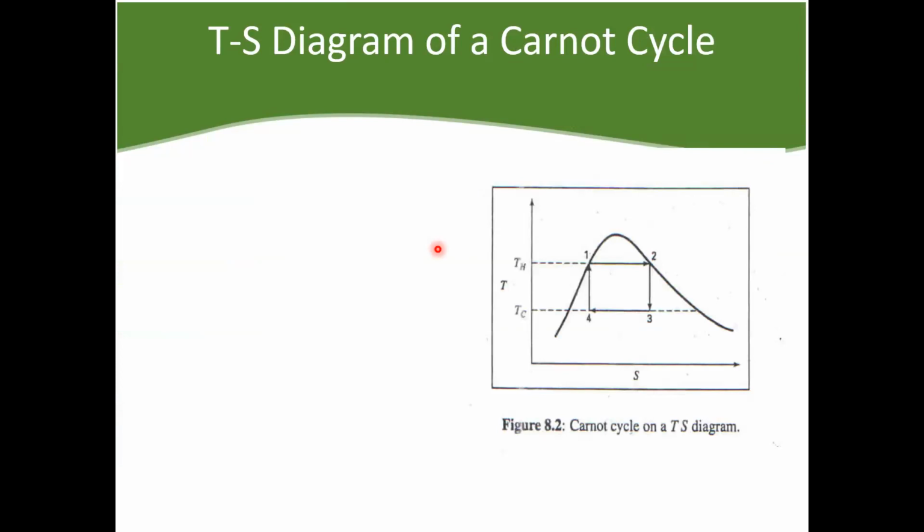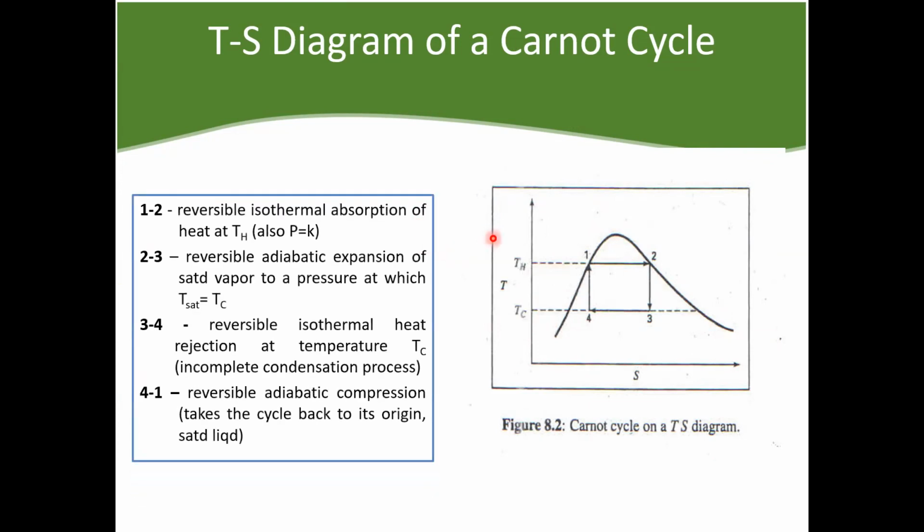So what does it look like on a TS diagram? By the way, the TS diagram is your best friend in this topic. You are expected to always draw a TS diagram. So practice drawing a TS diagram. It will guide you through the process of solving the problems in this topic. This is a Carnot cycle on this TS diagram.